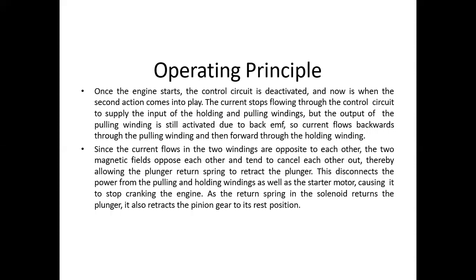Next, what happens once the engine starts. After the engine starts, we cannot keep the starter motor connected to the engine, because the engine would produce a reverse voltage to the starter, since the speeds of the engine crankshaft and the starter motor will differ. So we need to disconnect the starter from the crankshaft.